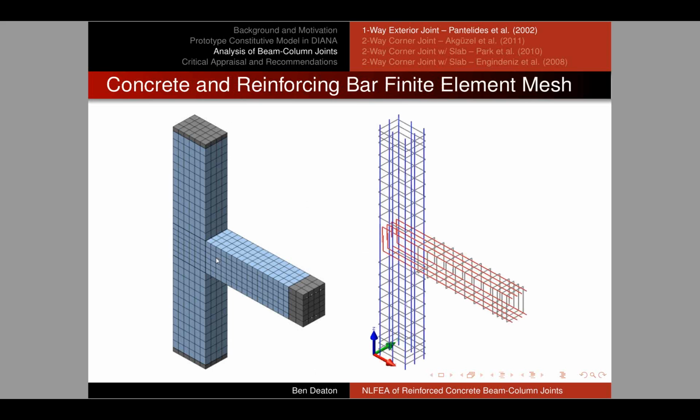So here's an idea of the type of mesh that I use in this study. So everything you see in blue contained the nonlinear concrete model. The regions in the darker gray color at the column ends and the beam end were given elastic properties and somewhat higher stiffness.